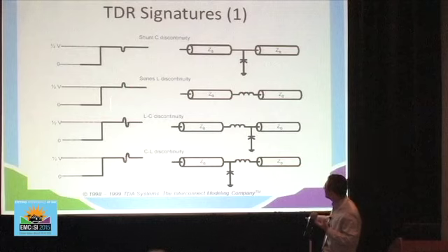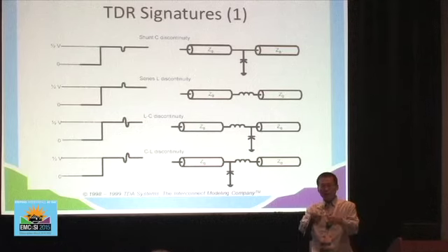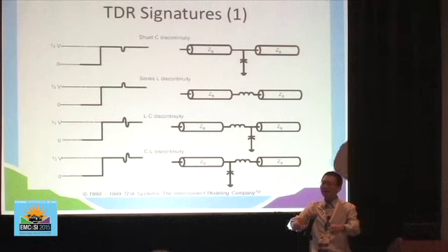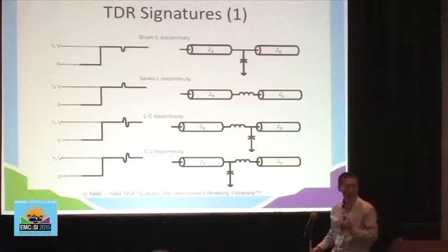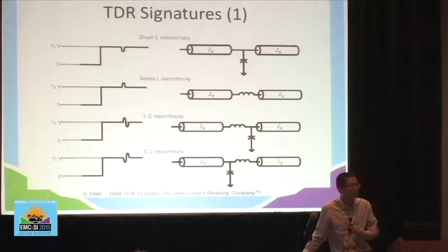Usually, you would see a dip first, because the vias are capacitive most of the time. And then you may have a peak here, because at the via to trace connection, the trace portion, because of the antipad, doesn't have the return path, so it's a little bit inductive. So often you would see this case when you have a via to trace connection. If this dip and the peak are getting too large, you need to tune your design.